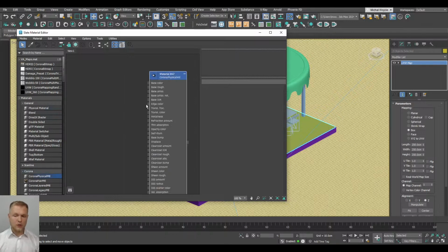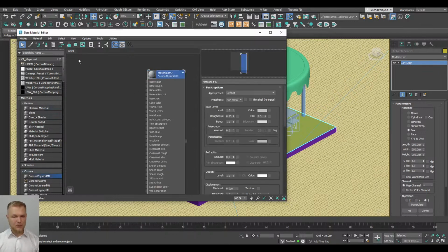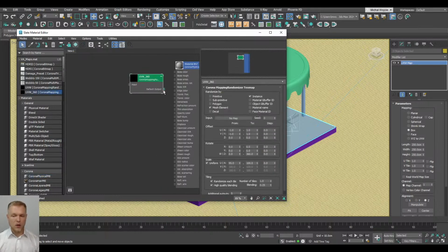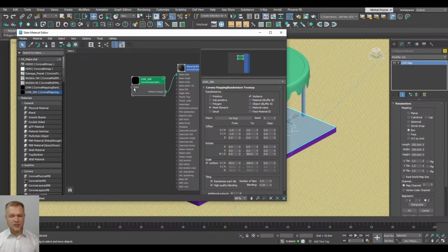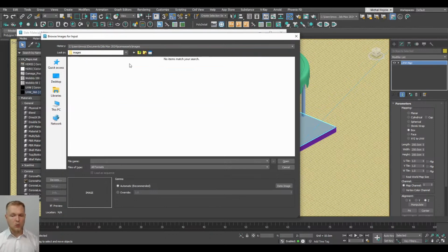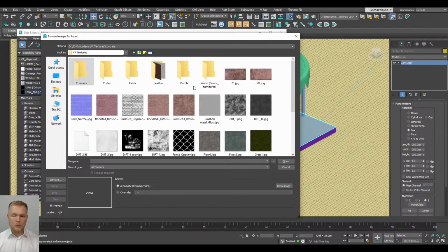Go to Physical Material first and select a simple material that's going to serve as our main floor material. Corona has a lot of amazing options to offer. For example, texture randomization, which is going to be set to mesh element and instance. We're going to also go for Corona Bitmap, and I'm going to be plugging in this map that our students during the training will be obtaining.